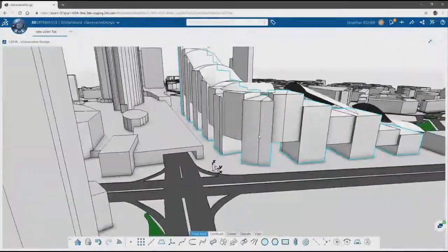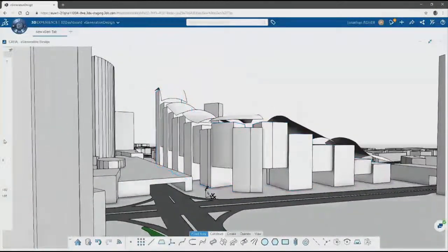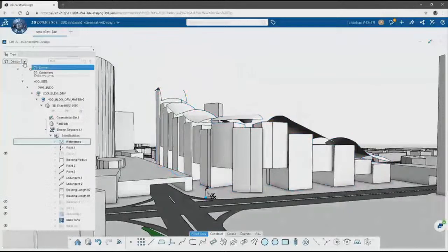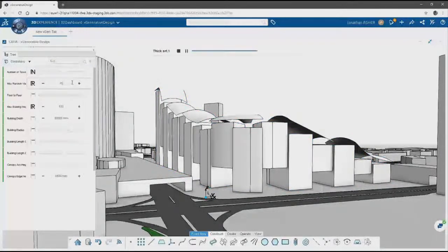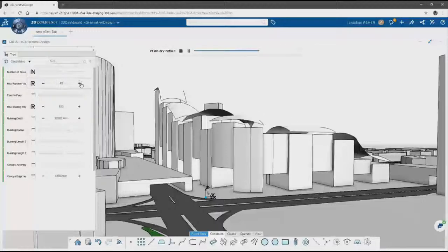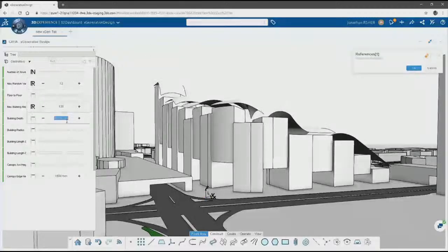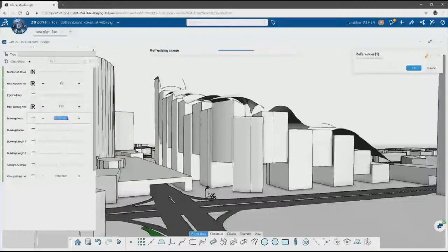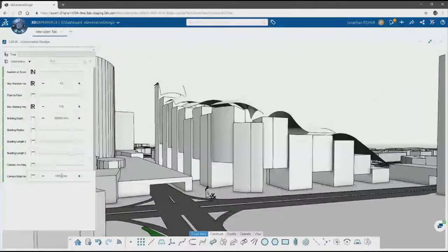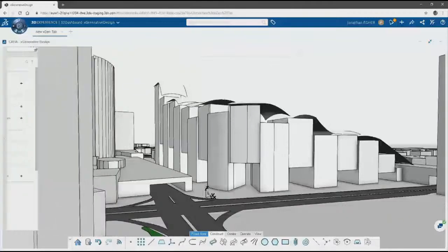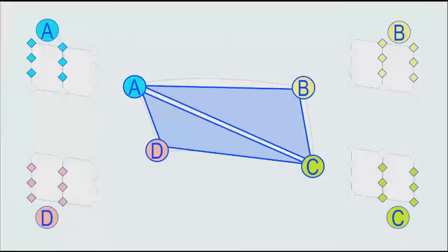So this is a building massing video that you'll see on our YouTube channel that will walk you through every step to model this building. Exploring some of the driving parameters through the controllers panel, you see how we can produce variation within the design space of this model. And what we want to do is single out one of these canopies. We're going to build an engineering template, and then we're going to use CATIA KnowledgeWare to instantiate that parametric engineering template across the canopy geometry.